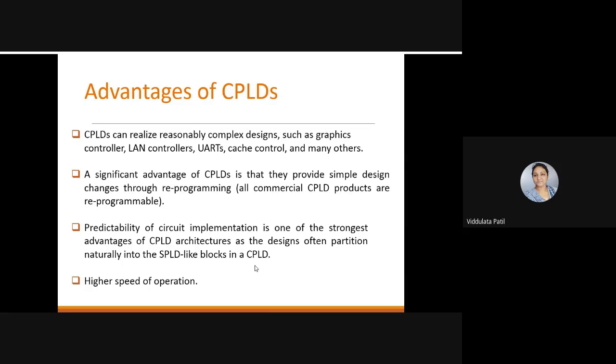Predictability of circuit implementation is one of the strongest advantages of CPLD architecture, as designs often partition naturally into the SPLD-like blocks in a CPLD. So you can predict whether the circuit implementation is going to be correct or not.